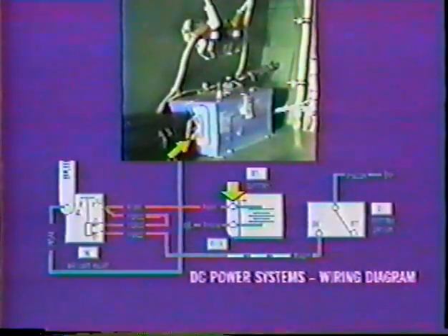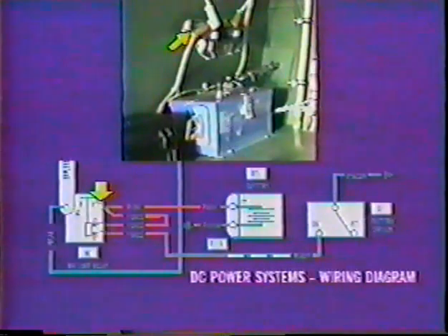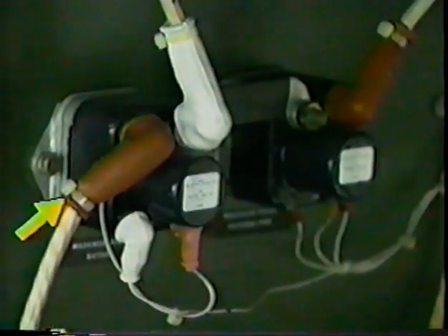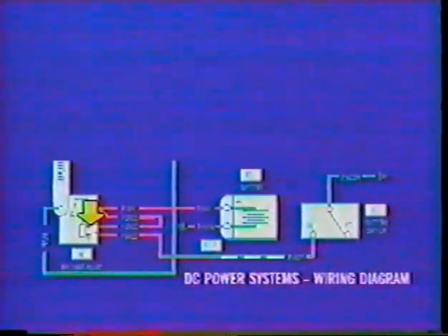Start at the battery and move along the positive wire to terminal A2 located on the battery relay. Continue following the jumper wire to terminal X1. This puts controlling power on the relay. All that is needed to activate the relay now is a ground.